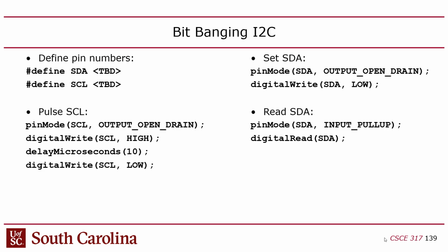The reason I say that is because Alex designed the circuit board, and this is determined when you design the circuit board. You have to choose pins on the ESP32 to route to the sensor's SCL and SDA. So these pins are locked into the circuit board design, and we'll tell you what those pins are. I don't know what they are. I don't think even Alex knows. But we'll figure that out because they used to be different last semester.